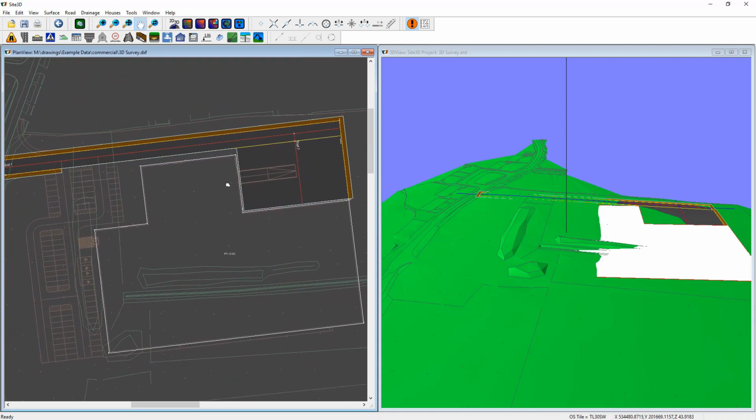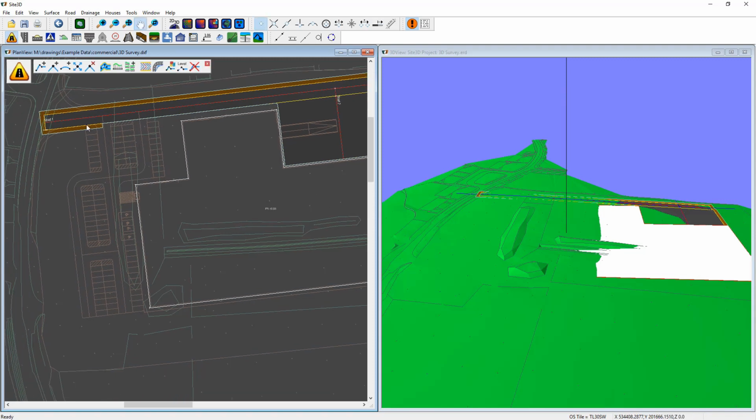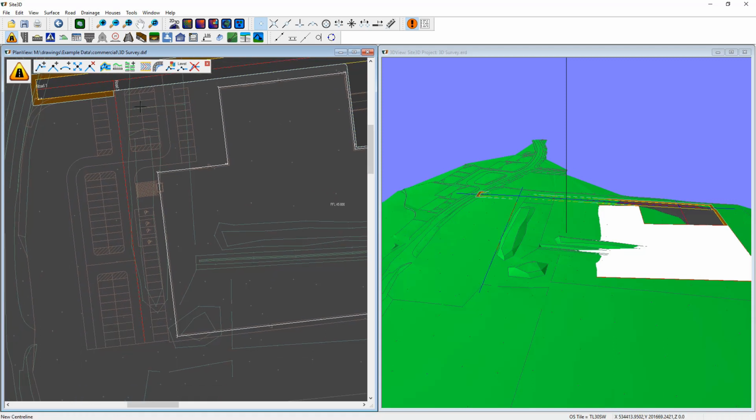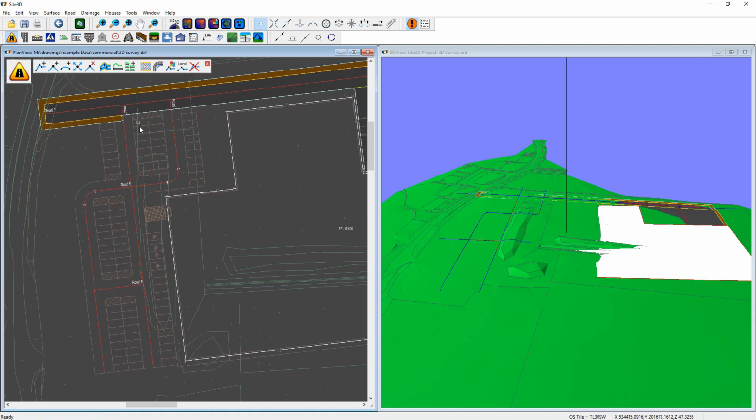Okay, so we've got that. Next thing is to insert these roads. Let's do that now. So very quickly, these look like fairly simplistic roads, straight line from here to here. Okay, let's just put in all the center lines at the same time. Snap to point, snap to arc, and then snap back to point. Okay, snap to point here, snap to arc, snap to point. Okay, and then finally this one here, from here to here. Okay, so we have the center lines in.